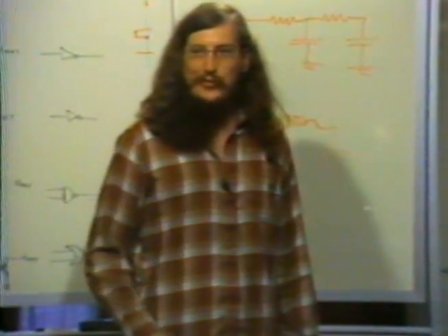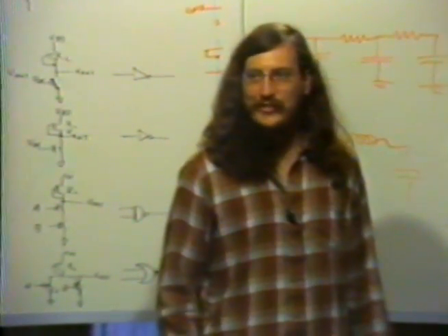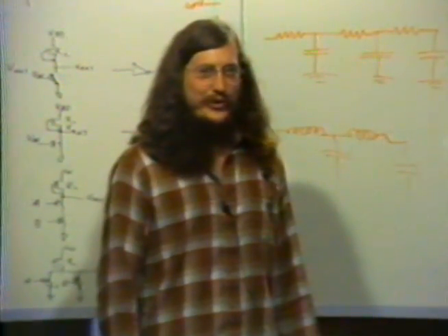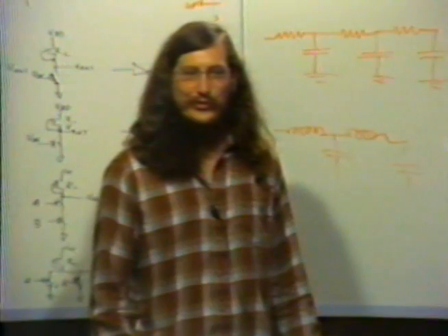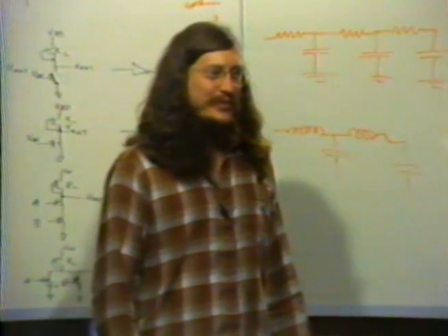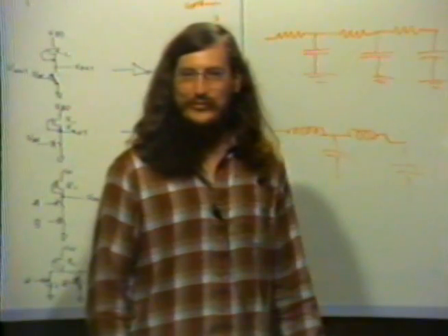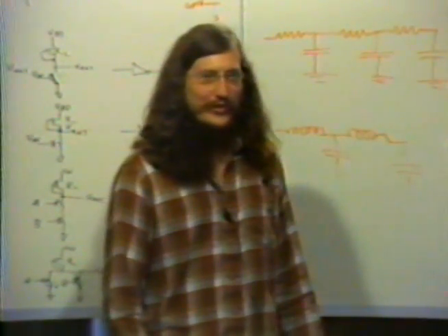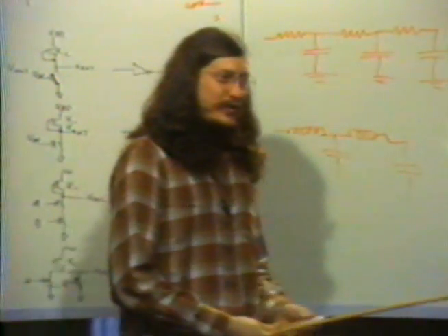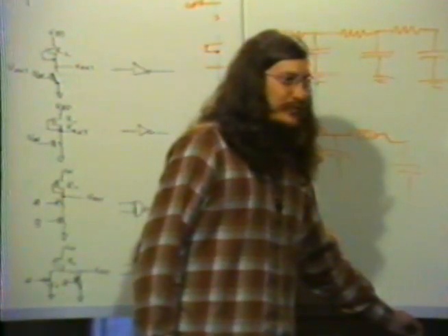In a stick diagram, if you want to connect green to red, you draw a black blob. And when you actually implement that, most commonly, that's done by going through the blue layer. There are technologies with a trick known as buried contacts, which allow you to directly connect green to red without coming up to the metal layer. We don't typically use that, and most of our stick diagrams don't indicate that it's done one way or the other. Okay? The blob is big, though, physically, so you don't tend to use that to speed up lines? To speed up lines.